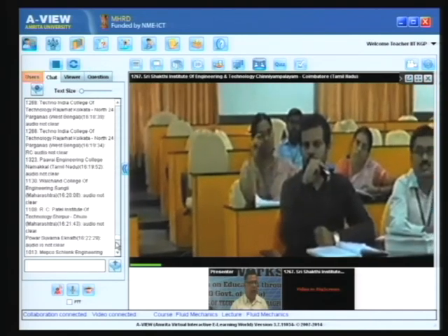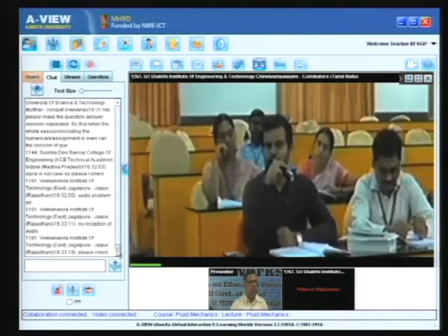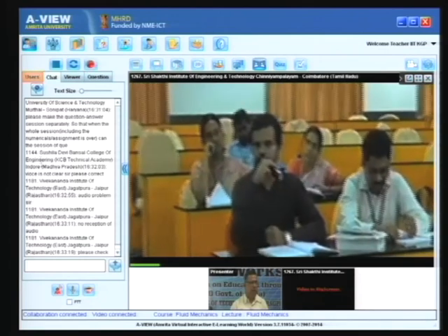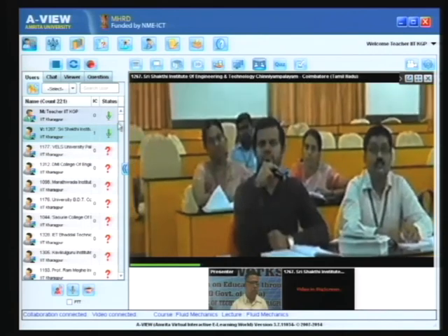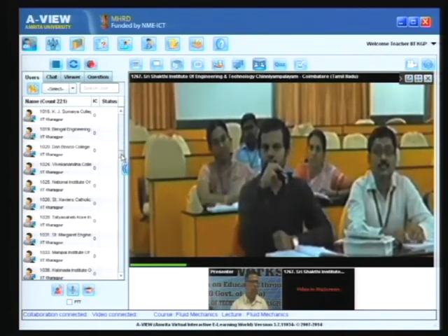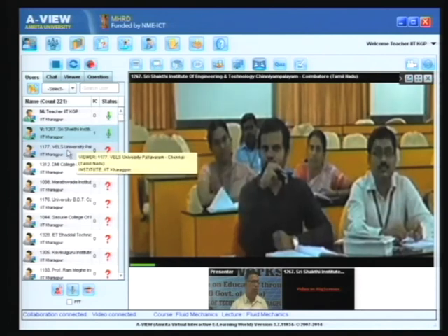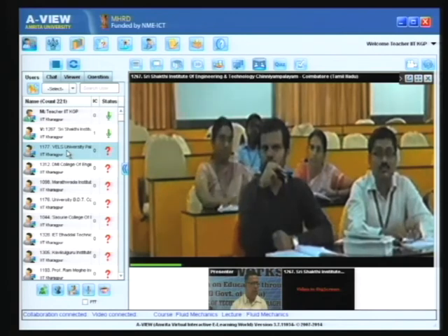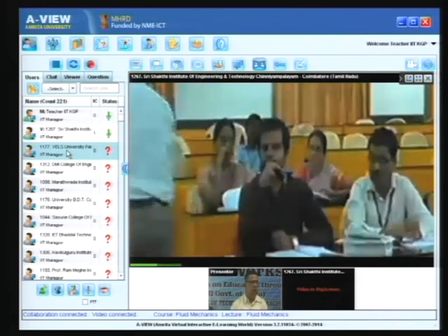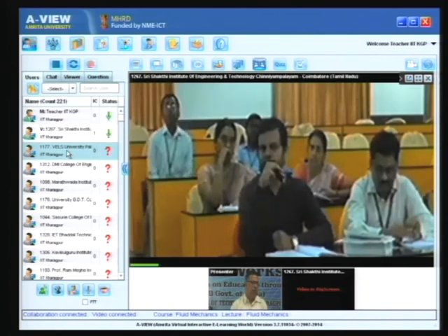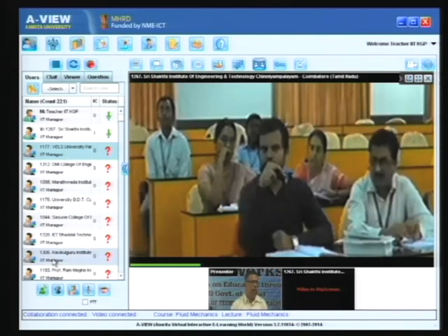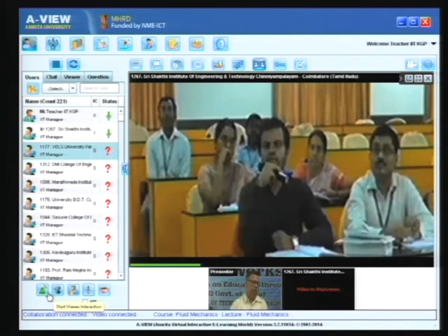For the interface between the two liquids, if you neglect surface tension effects, the pressure will be continuous. So, you equate the pressure from the equation obtained for the bottom liquid with the pressure obtained using the equation for the top liquid, and you will get a link between the two constants. It is a matter of working it out, but roughly both will be parabolic in nature.